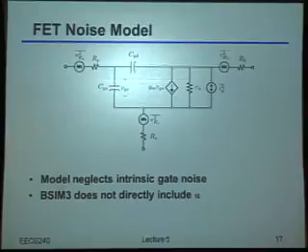And secondly, depending upon which version of the SPICE model you're using, remember BSIM is one of the industry standard models that's out there. BSIM 3, I should say, is about 5 to 10 years old now. So actually, most people use what's called BSIM 4. But long story short, just be careful because your model may or may not include all of the short channel effects completely accurately.